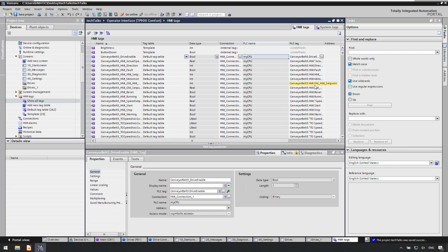It wouldn't even have to be a service engineer, would it? You wouldn't need to be a skilled engineer to run a program like this. A program like this could even be running on the network automatically, just monitoring the projects around the factory, making sure that there are no changes introduced. Or, let's say it runs daily or weekly, grabs the projects from the PLCs across the factory floor, and if it sees that there is a difference between the project that it has and the project it had last week, it could automatically record this information, automatically generate a list of differences, and maybe notify someone.